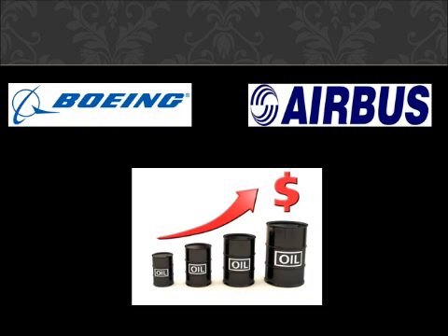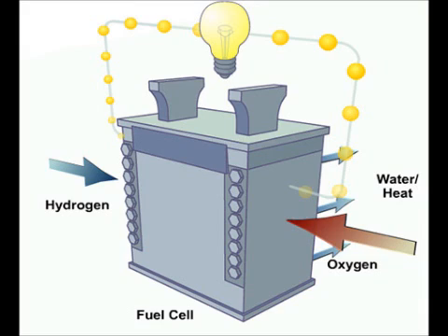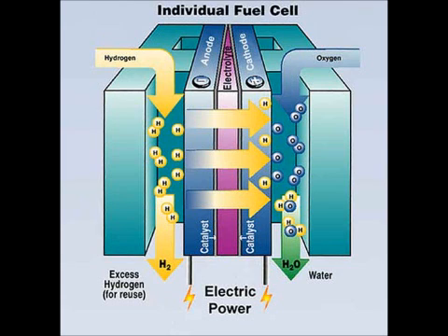fleet of aircraft. To begin our discussion on SOFC APUs, we shall first take a look at what a fuel cell is and its working principles. A fuel cell is essentially a device which converts chemical energy directly into electrical energy via chemical reaction with an oxidizing agent such as oxygen. During operation, the hydrogen in the fuel cell will react with oxygen to produce electricity, and the waste product from this reaction is just water. As long as hydrogen and oxygen are being supplied to it, the fuel cell will be able to generate electricity continually.